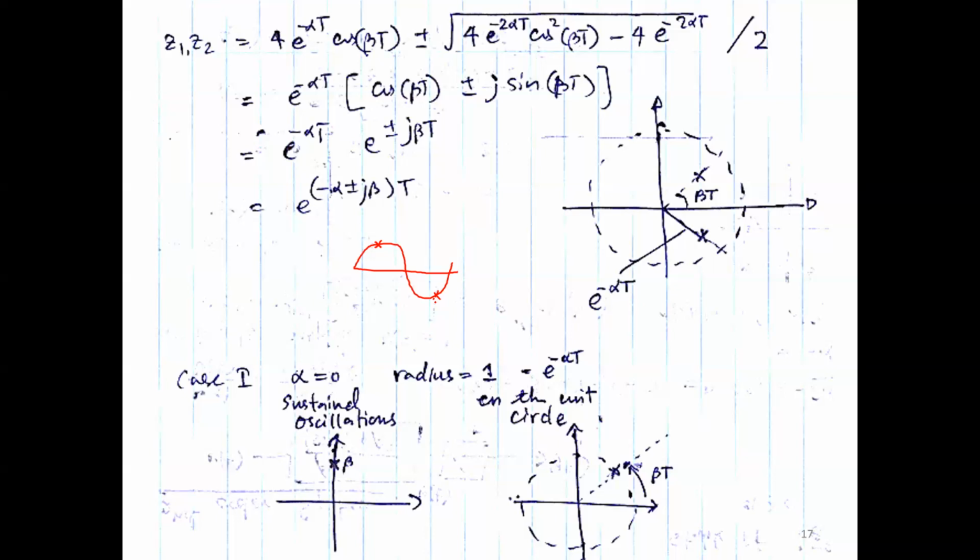Now, if you think of a signal and look at this signal, it's not purely sinusoidal, right? It has a lot of sinusoidal waveforms. In that case, you pick up the highest frequency component in the signal. If it's a multi-frequency composite signal, it has 5 hertz, 10 hertz, 50 hertz, let's say. You pick up the maximum frequency, 50 hertz, and multiply by 2, 100 hertz. And that is your minimum sampling frequency. But that is not adequate.